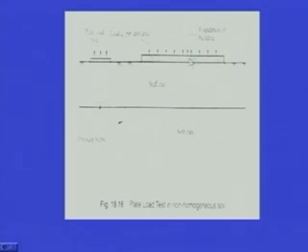Now, in that case the pressure bulb for the same intensity also goes beyond the boundary of this upper stratum. So, it also penetrates into the lower stratum. In this case, the load characteristics of this particular stratum are not accounted for if we conduct the test on the smaller size plate. So, we will have to be very cautious.